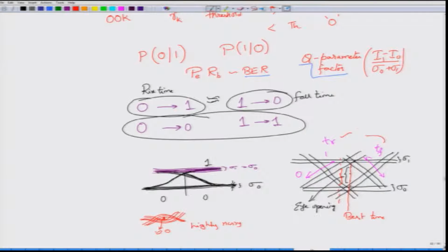If you measure, it is possible to find out how much chromatic dispersion existed. So, if you know the rise time of the pulse before propagating through the fiber, then you can look at what the situation would be after it has propagated through the fiber, and from there estimate the chromatic dispersion. Okay. It is also possible to estimate the BER as well as the Q factor.